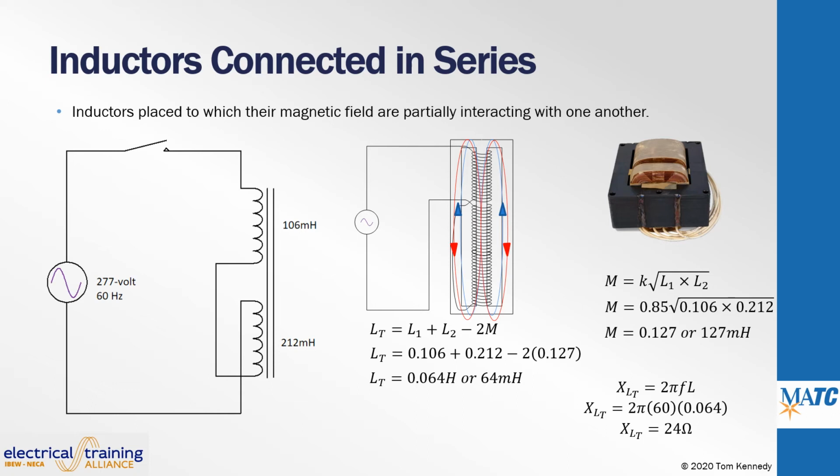These coils connected to a 277-volt source in this manner would allow 11.5 amperes to flow. This can express the importance of connecting inductors so that the polarity of the connections are correct. A small error in wiring could result in a large current that can damage electrical equipment and create a hazard.